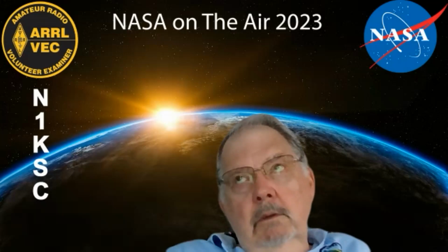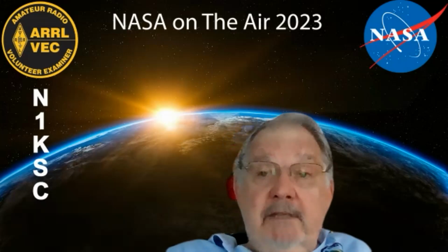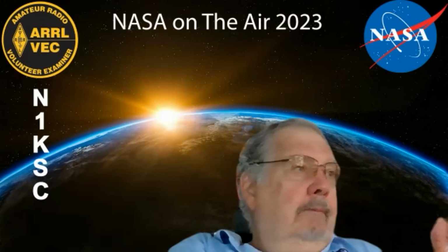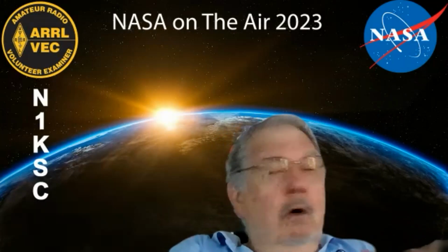JT65, I think you can actually send some other information. There's one called JS8Call, which I've used, which isn't part of the same software suite, but it's based on the FT8 type protocols. And it's actually message passing, where you type in a message and you can direct it to a specific call, or you could just do a CQ with it. It works pretty good. It's not fast. It's a fairly low baud rate, but it works pretty good.